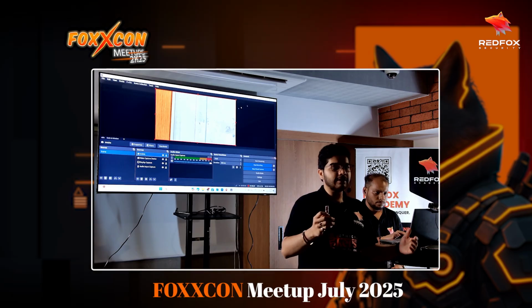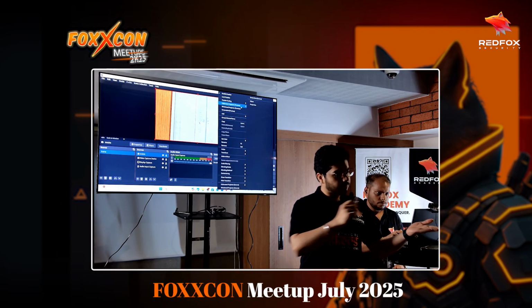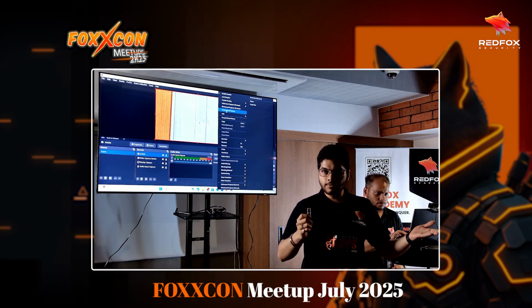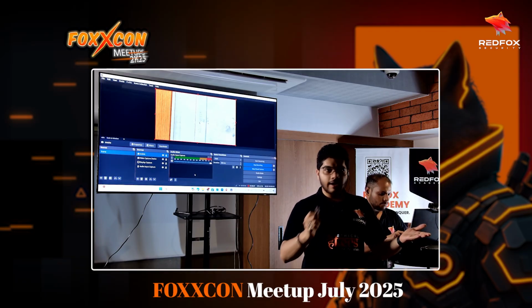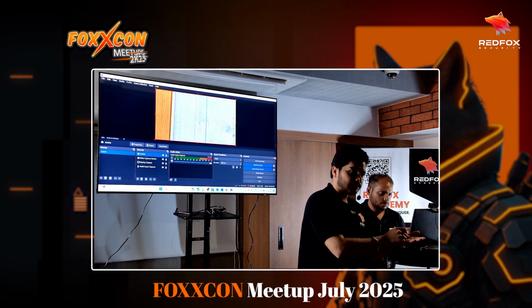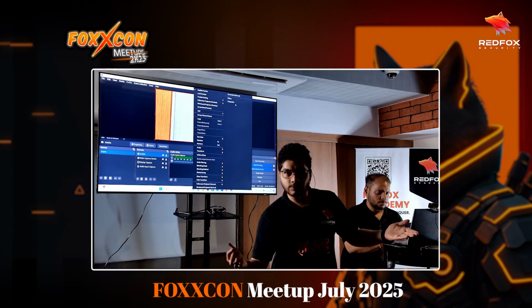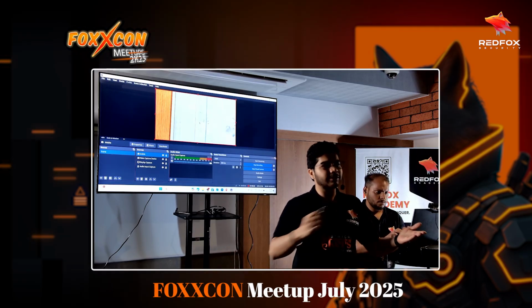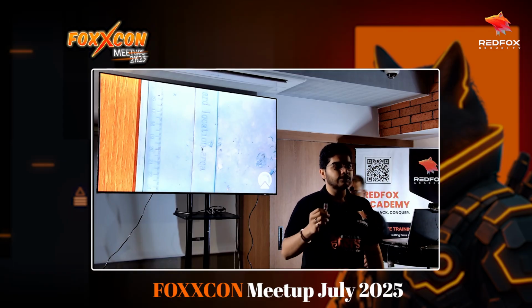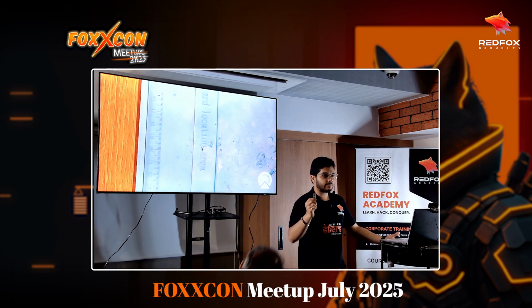So the connectivity between, let's say, an embedded device and this should be power to power, ground to ground, transmit to receive, and receive to transmit. Because if you send commands, they will be received on that device, and if it is sending certain logs, you will be able to receive them on your computer. If you do transmit to transmit, that's going to just mess things up. So that is one thing that is different in terms of how you connect this to an embedded device.